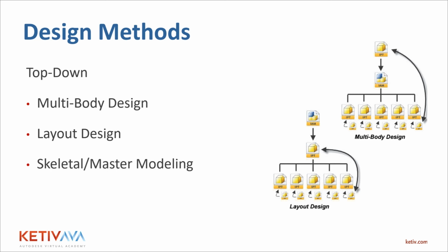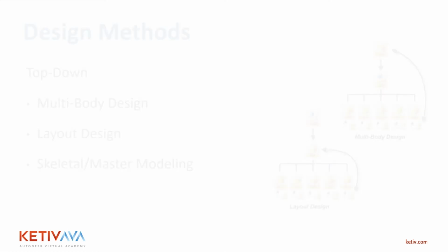So with that said, I'm going to go ahead and conclude. We showed you a few ways you can increase performance. Some were more immediate than others. The way I just looked at is somewhere in between, where you do have to invest time, open up assemblies, create these lower levels of detail, and create shrink wrap substitutes or just substitutes in general. But this one would be very effective, right? Just changing your design methods. It would just require a more fundamental change in how you model things. So with that said, I'm going to go ahead and turn it over here to Nigel.